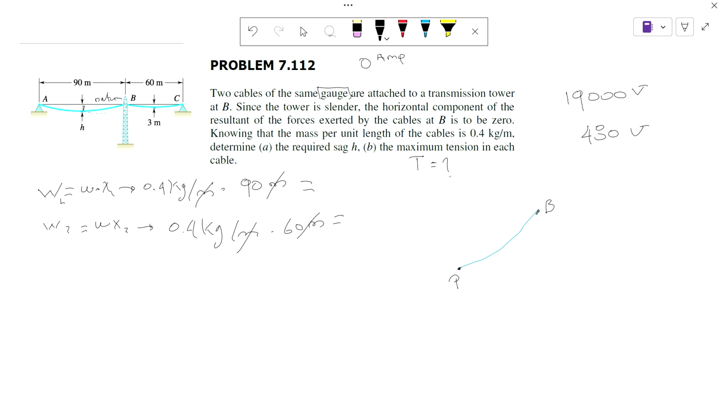So obviously there's a tangential force, which is this tension, and there's a horizontal force, tangent as well to this curvature, that is my TPX. The wire of the cable has weight, W, and that is precisely how we form the force parallelogram, or in this case it's a triangle. This is how we form the triangle.